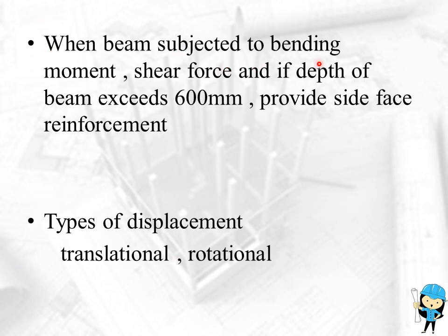When a beam is subjected to bending moment and shear force, and if the depth of the beam exceeds 600 mm, provide side face reinforcement. Side face reinforcement is equal to 0.1% of gross area.